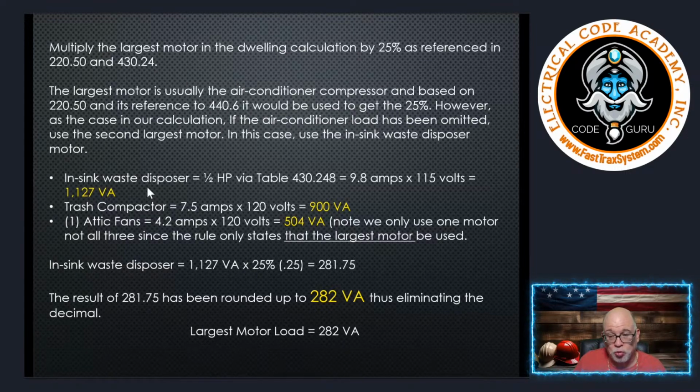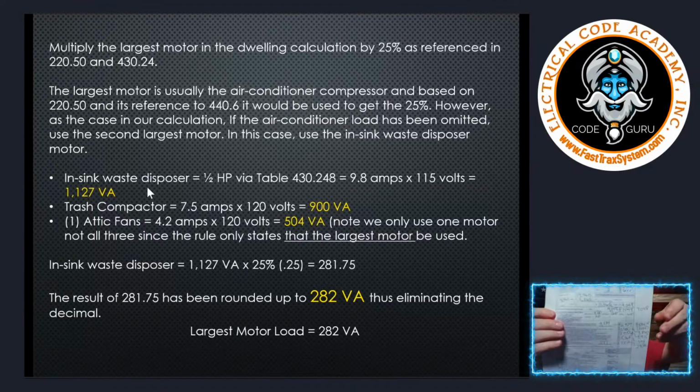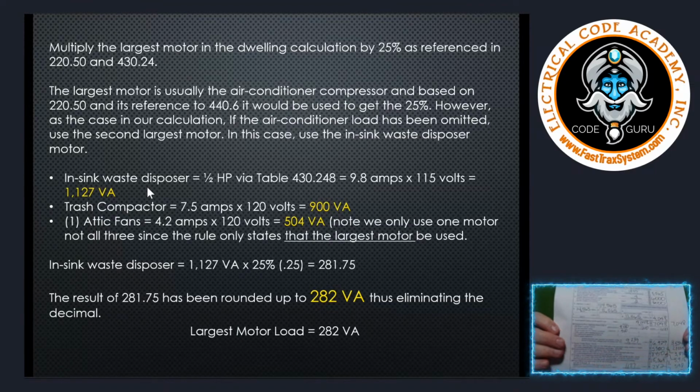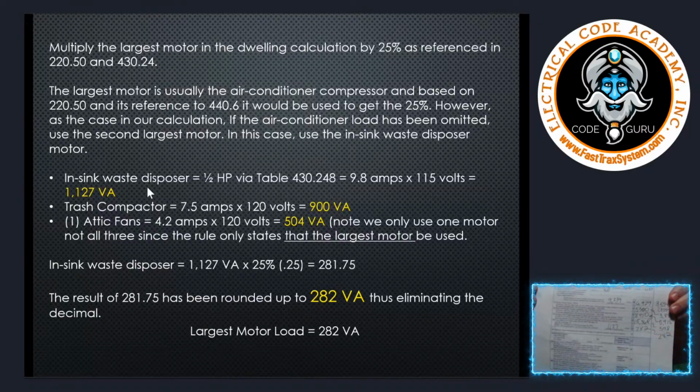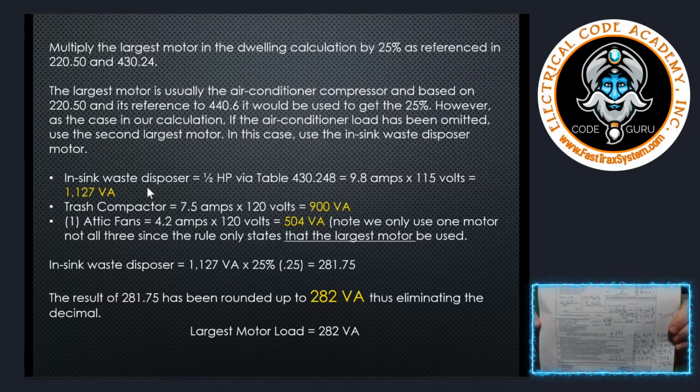So it does have neutral loads, right? So that last step for the neutral definitely accounts for 282 amps. So I'm going to write that down as 282 for my neutral. Okay. So far, this is what it should look like to you folks. Look how I filled this all out. And look, I've got neutral loads right there beside it. We'll verify those here in a second, but we're good to go.